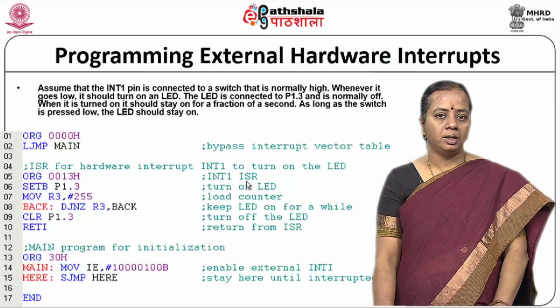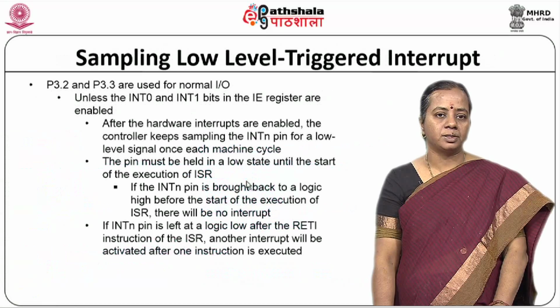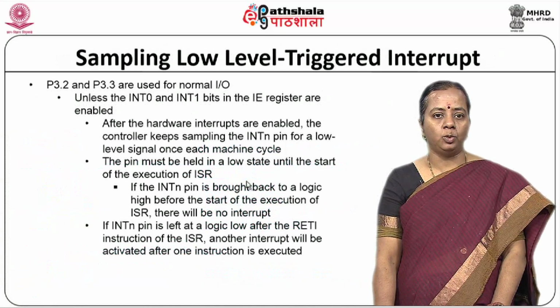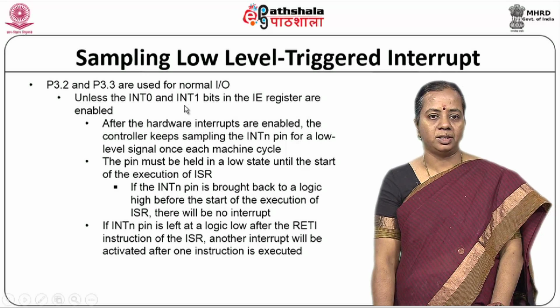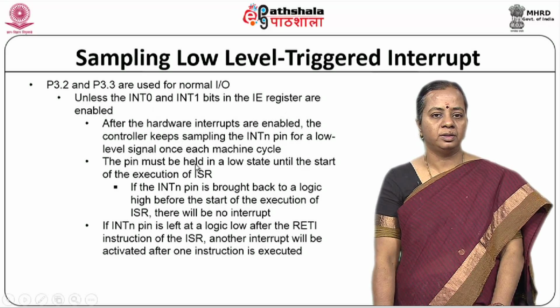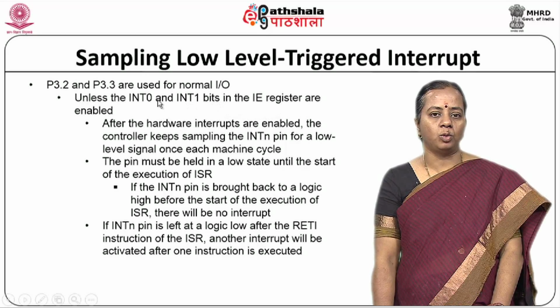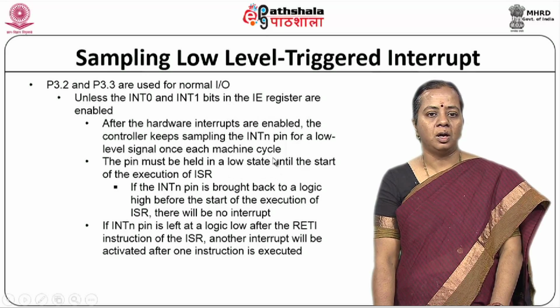So, here when you look at P3.2 and P3.3, they look like normal IO, but if the INT0 and INT1 bits in the IE are enabled, then it will be a different case. If the IE register is enabled, these will be used only as external interrupts, otherwise you can use them for normal operations also.